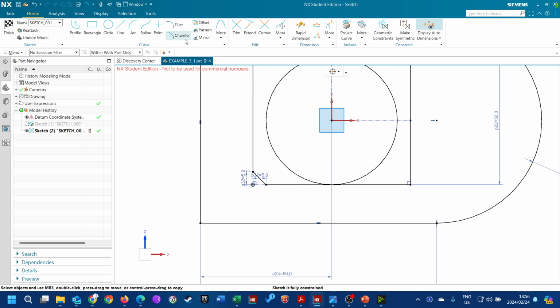And now we want to create the round or the fillet. Same difference. So you have different methods. You can use the trim one or the untrim. So the untrim will leave the lines. The trim will remove the lines. The same as here, we want to remove the lines. So we click the one edge, click the other edge, put it where we want it, and just type 10 millimeters, enter, and it added our round.